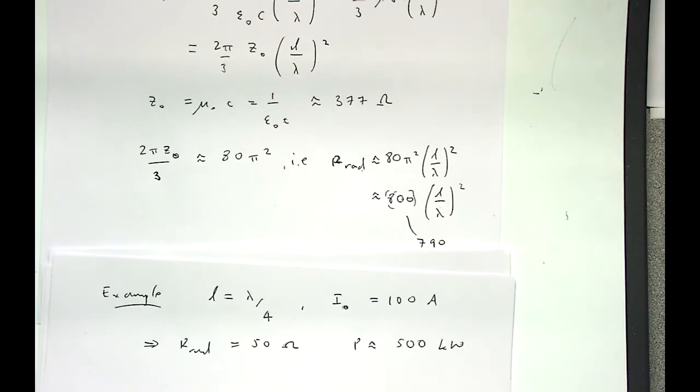The Winter-Hill transmitter over there, which I'm going to talk about a few times, is about 1/4 of a wavelength long. Clearly it's emitting over several different frequencies, but order of magnitude is about 1/4 of wavelength, about 100 amps, about 500 kilowatts. So don't pin those numbers down too hard in your mind. So that's our concept of radiation resistance. It's not like a proper resistance. It's really to do with the way that the electrons, as they're moving upwards and downwards, are freeing away, the rate at which they can free away these photons.